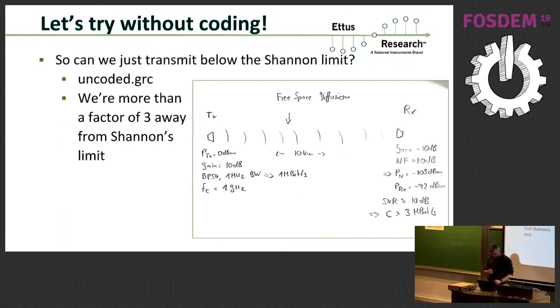All right. So here's, I'm not good at computer graphics, so this is how I make pictures. This is just a very, very hypothetical setup. So we have a transmit antenna, receive antenna. I use the number 10 a lot because in dB that works out. I have a transmit gain of 10 dB, a receive gain of 10 dB, a noise figure of 10 dB, 10 kilometers distance, and these are all very even numbers.